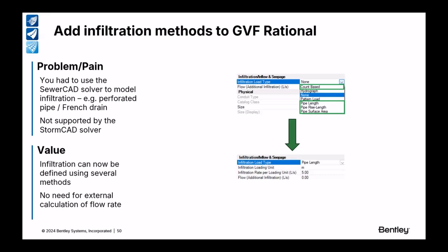Okay, next slide, please. Just got a couple more to go on the drainage side here. A little bit of explanation on this. This might be relevant to road, but it's certainly relevant to railway design as well. If you're designing railway in cutting, you're going to be looking to put some kind of porous conduit, sometimes called a filter drain or a French drain, to accept the runoff from the cut slope, as well as the track surface, maybe the road surface.